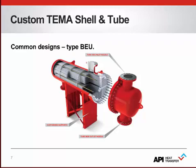Next, we have a typical BEU type exchanger. You can see the B-style front head in the front with the tube side inlet and outlet nozzles attached, pointing up and down. Again, a simple E shell is utilized here, with the U rear head designation shown simply by the bent U-tubes within the shell.